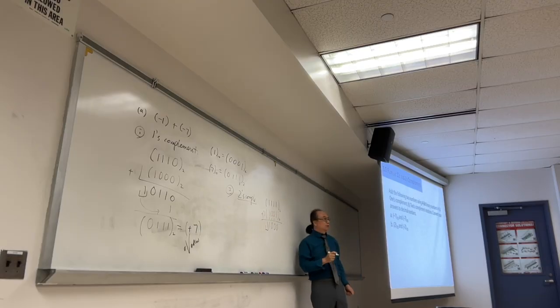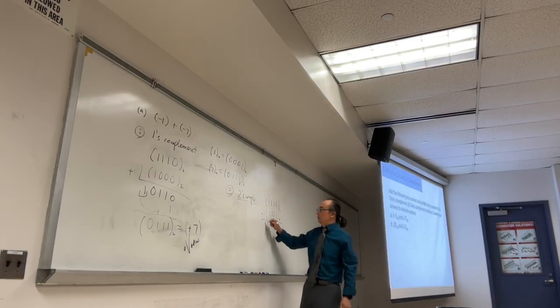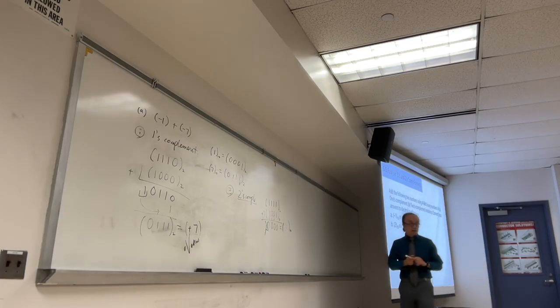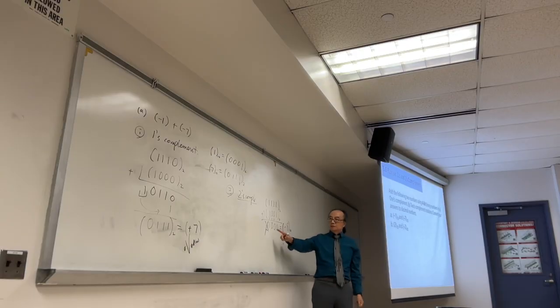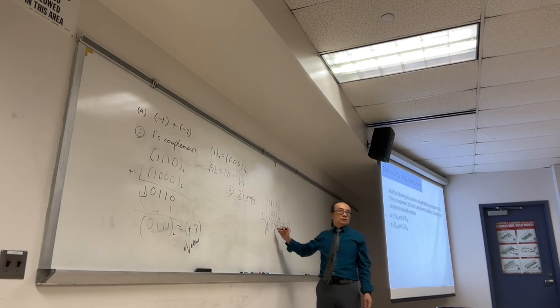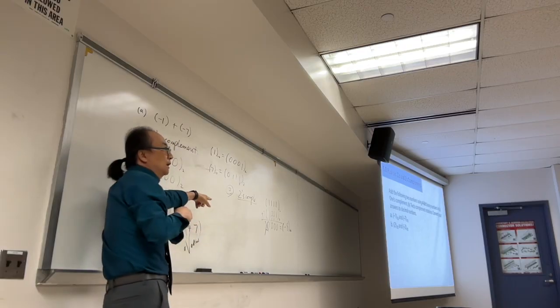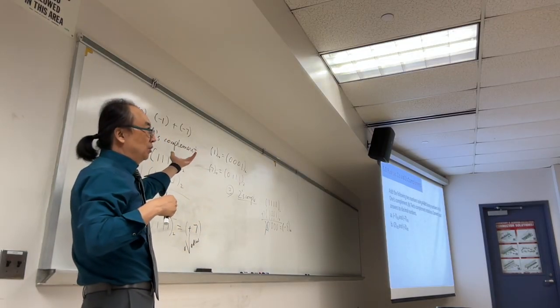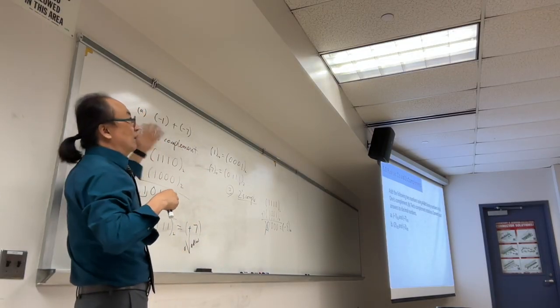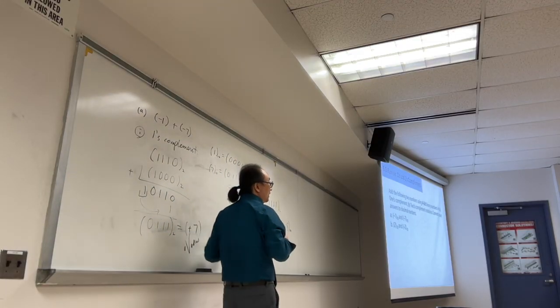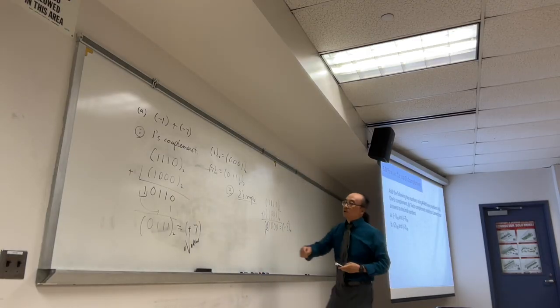For 2's complement notation, for addition, if there is a carry, we simply ignore. And what is this in decimal? Exactly, -8, not +8. Okay, because start with the 1, it's a negative. So as you can see, 2's complement, we can go down to -8, so there's no overflow. And if we have more than -8, it's going to be overflow. And for the 1's complement, we can go up to -7. There's no -8 in the 1's complement.